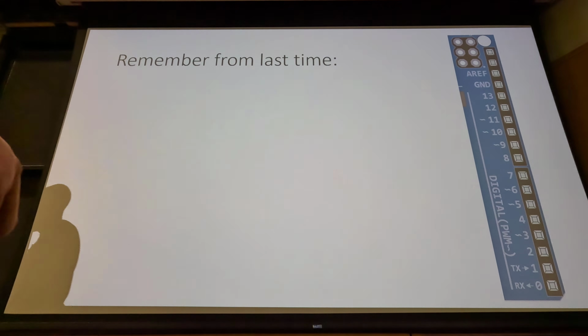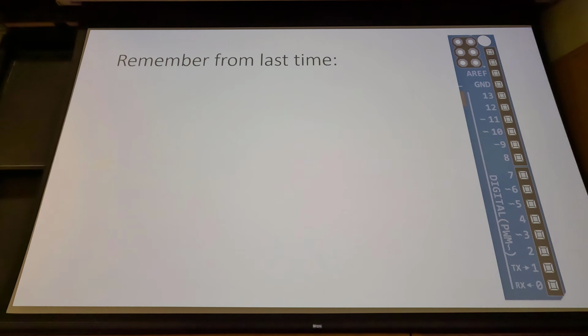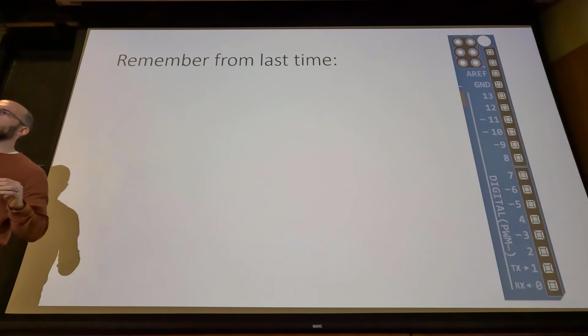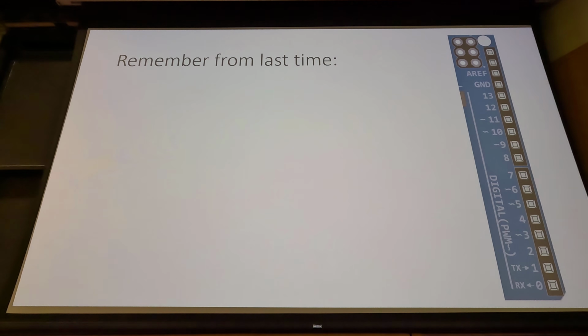I briefly mentioned last time, these are pins that can be controlled by software and can function either as inputs or outputs. If it's an output, it acts like a voltage source. It can provide current, it can set a voltage to something that it's controlling, but it's digital, it can only be high or low. I haven't really used the word analog much, but for pretty much the first half of this course, we were talking about analog circuits where voltage could vary continuously.